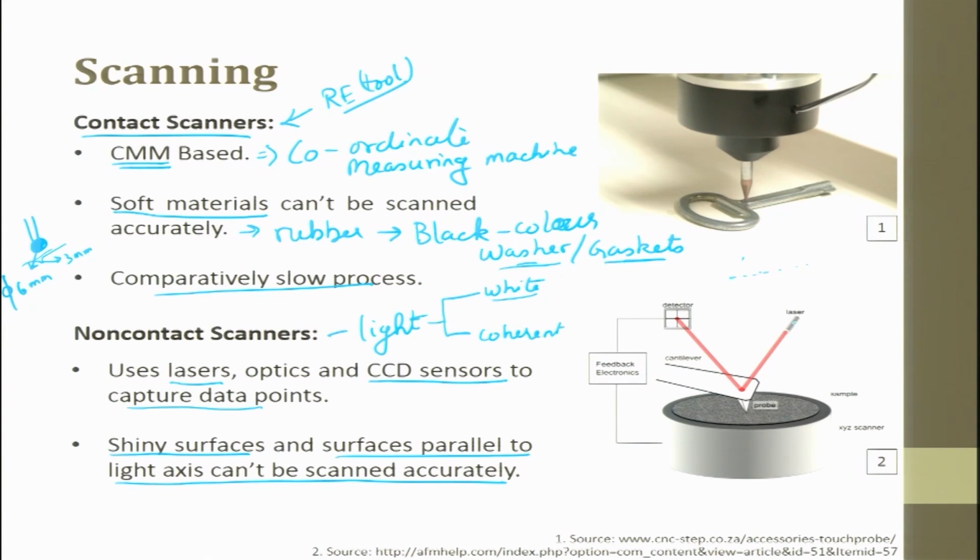So here we have a laser. This is nothing but an atomic force microscope, wherein if you want to get data in the nanometer range or Angstrom range, you can use this atomic force microscope. Here there is a laser which hits the back side of the probe, where you have put a reflecting surface. The laser hits, reflects, and falls on a diode. This diode is a photodiode which is divided into 4 parts.